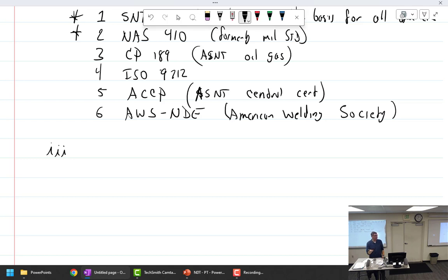But let's just say that I find a crack in my motor mount and I want to do a weld repair on it. I've never welded before, but I've got a couple YouTube videos. So I go to AC 43.13, and it shows in there how to do a weld repair on a motor mount. So I do it just like that. And I weld it, and it looks like the eagle has pooped all over. We used to say that in welding, it looks like bird shit. And you're like, wow, well, I did it. Can I go for it? Well, hold on, you're not supposed to go off 43.13, you go off the maintenance repair manual first, right? Oh, what if it's an antique airplane? What if I just choose that?